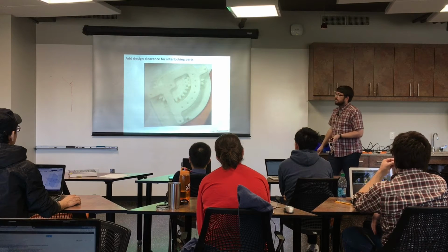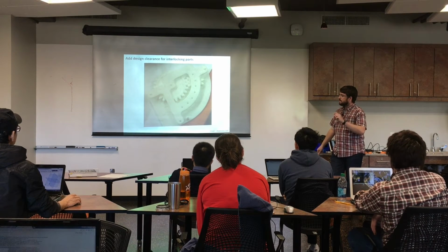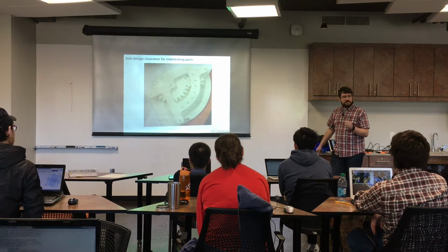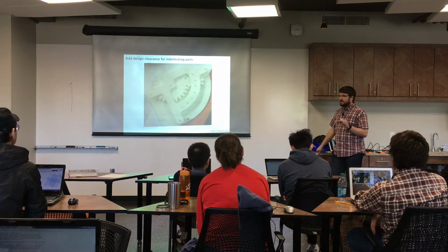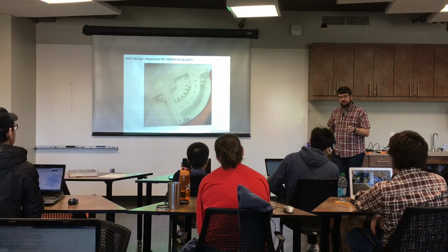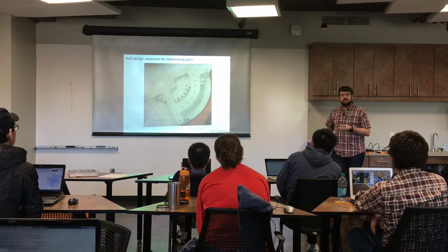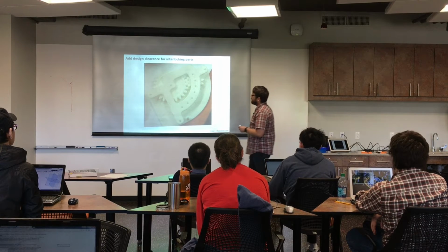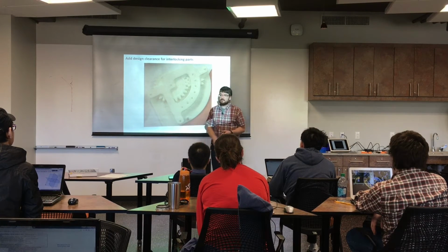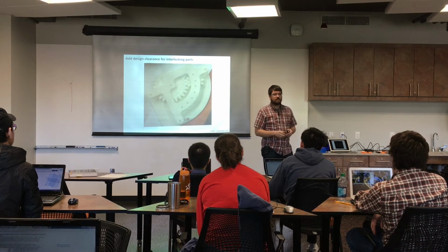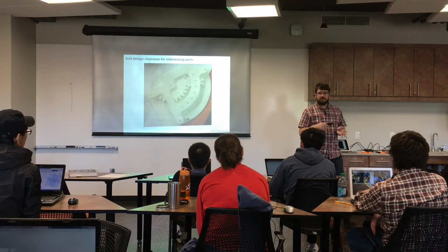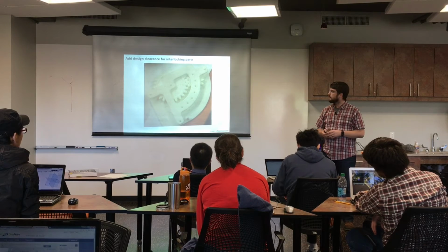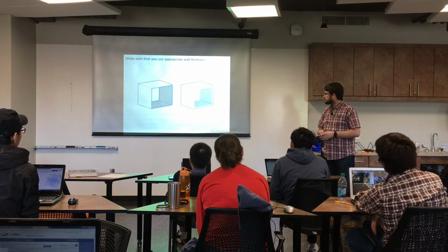On 3D printed parts, true dimension clearance, if you need something that's tight, something that's going to be a press fit, maybe 5 to 10 thousandths of clearance, I would stay on the upper end of that, is a pretty good number. If you have something that needs to move and have a free fit, like those gears, or you need a pin to be able to slide through something, somewhere on the order of 15 to 20 thousandths is a pretty good clearance number.